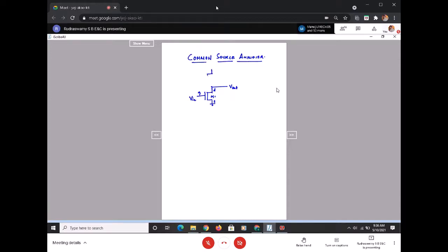And that was possible with this being the gate, this the source, and this the drain of my PMOS, which I called M2, where the gate is shorted with the drain. The source of this PMOS goes to VDD. We ensured that M2 should operate in the saturation region. This is what our requirement was.